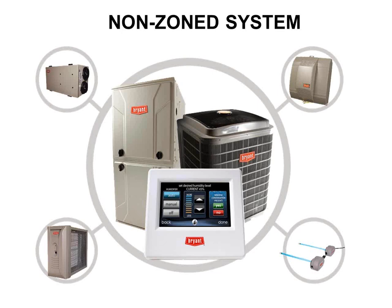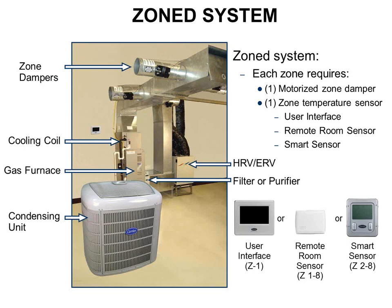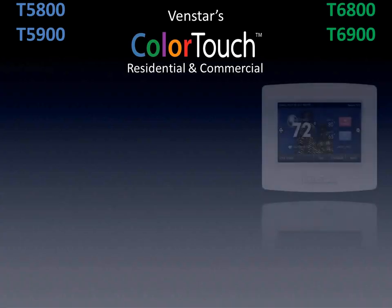You can do non-zoning systems with these stats. It'll control your humidifier, your furnace, your AC, your Bryant and Carrier ERV, your air purification, your UV lights, all that kind of stuff. And you can do fully zoned systems with dampers and all of that kind of thing. The cool thing about this zone damper system is there's no bypass involved, because since we know the static pressure and we are directly controlling the speed of the fan, we don't need to have a bypass when the damper starts shutting down. We just change the blower speed. So it works out pretty cool in that regard.